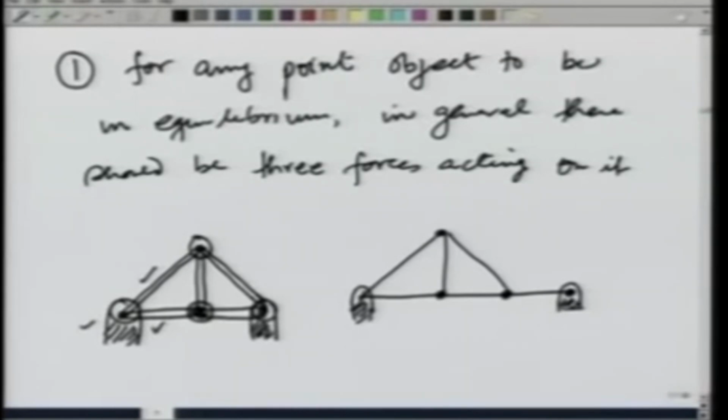However, the moment I do that, this joint will not be in equilibrium, because this is acted upon only by 2 forces, one by this fixed joint and other by this rod. So, I have to provide one more member to bring this point into equilibrium. The moment I do that, I have one free end of this member here, which also has to be brought into equilibrium. I could provide one rod this way and one rod this way, and this entire structure would be capable of remaining in equilibrium. This is a truss, a plain truss. So is this.